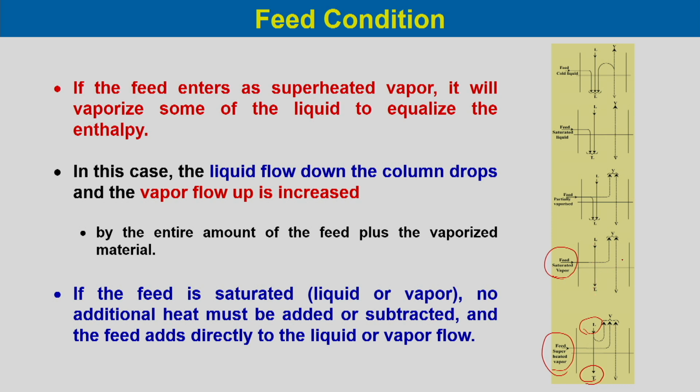So, it will just directly add with the vapor which is coming down. So, with the entire amount of the feed, the liquid flows will not change below the feed tray, whereas the vapor flows will increase by the amount of the feed flow.